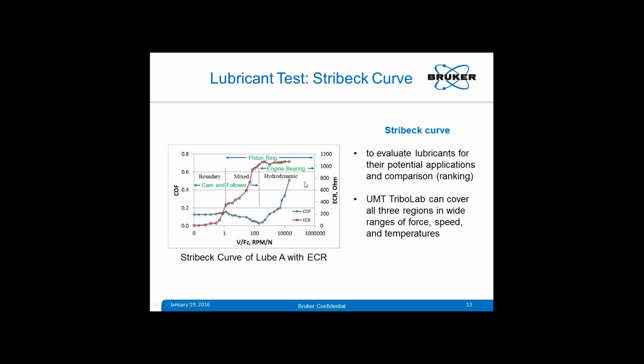In UMT TriboLab, we can also measure the electrical contact resistance between the two friction couples, between the two contacting surfaces. And you see the ECR data here. When there is a film, the ECR value is really high, meaning that there is a lubricant film present between these two contacting surfaces. As we go to the boundary, where the two surfaces are actually in contact, you see ECR is dropping because two metallic surfaces are in contact and the electrical contact resistance between them is almost zero. So this also can be measured and correlated.